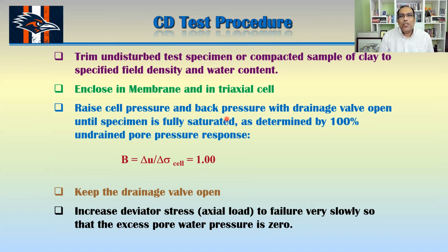So we have to make sure that the structure doesn't fail when the soil is completely saturated. Okay. So when we talk about shear strength, it's kind of implied that it's the shear strength when the soil is completely saturated. We don't say, "Hey, what is the shear strength of the soil when the soil is completely saturated?" Because you don't need to. It's kind of implied. Okay.